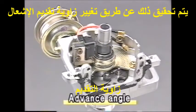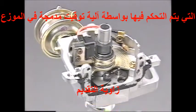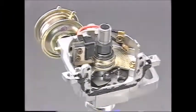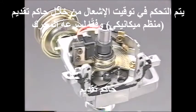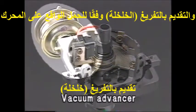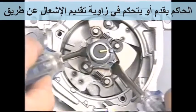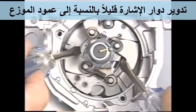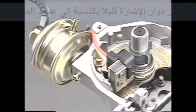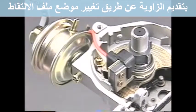This is achieved by altering the ignition advance angle, which is controlled by the advancer incorporated in the distributor. Ignition timing is controlled by a governor advancer according to the engine speed and by a vacuum advancer according to the load on the engine. The governor advancer controls the ignition advance angle by rotating the signal rotor slightly relative to the distributor shaft. And the vacuum advancer controls the advance angle by changing the position of the pickup coil.